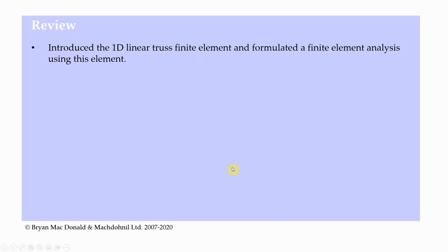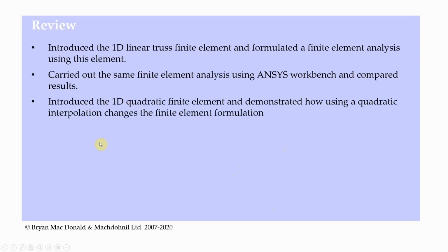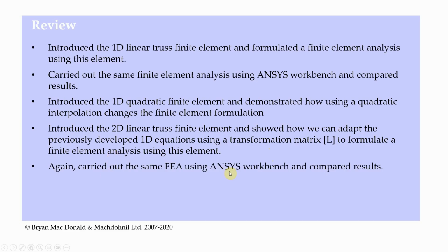Let's have a review of what we went through in this video. First of all, we introduced the one-dimensional linear truss finite element, and we formulated an FEA using that element. We then carried out the same finite element analysis using ANSYS Workbench, and we compared the results. We then introduced the 1D quadratic finite element and demonstrated how using a quadratic interpolation changes the finite element formulation. We then looked at the 2D linear truss finite element and showed how we can adapt the previously developed one-dimensional equations using a transformation matrix to formulate an FEA using this element. And again, we did that in Workbench and compared the results.